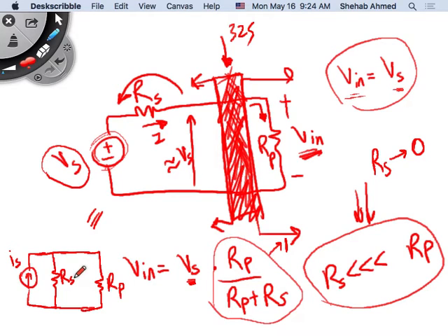And then there's a corresponding logic if a sensor is represented as a current producing device. We said yesterday some sensors can be represented as voltage producing devices, such as maybe a micro generator that is connected to a mechanism that measures flow. This micro generator is producing a voltage, right? This is represented as a Thevenin equivalent circuit this way.